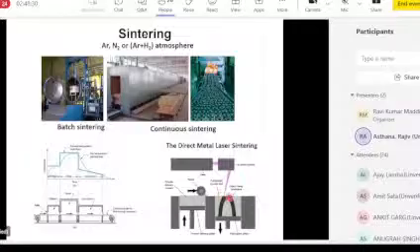So you're sintering selectively a certain range of powders. And this is how you build up layer by layer the actual part. So instead of sintering a bulk part, you sinter the powders in exactly the shape that you want to form.